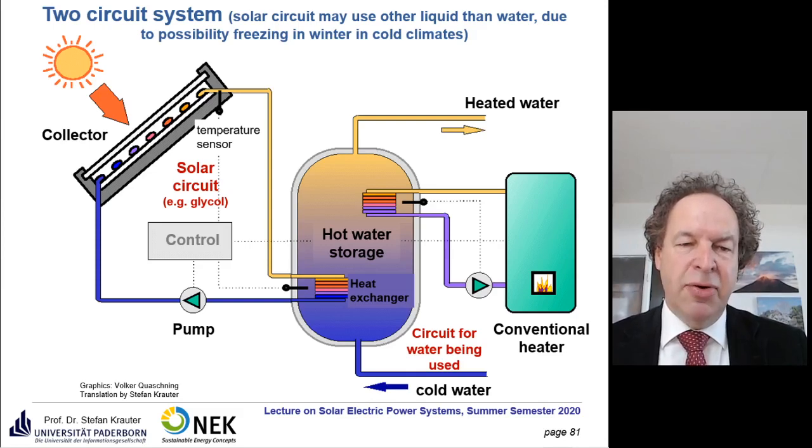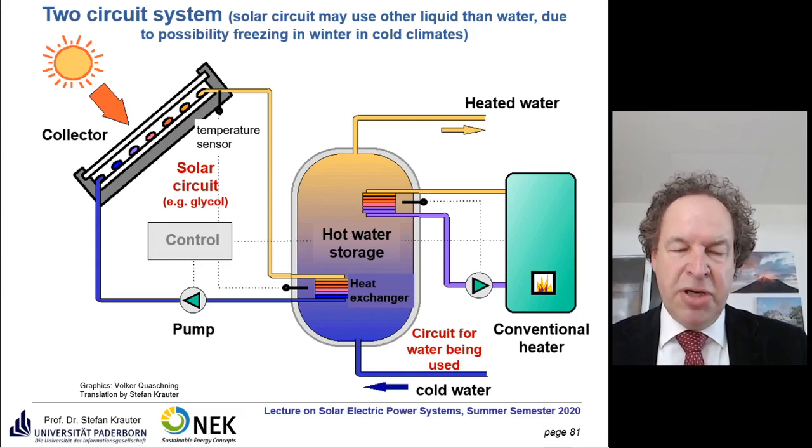Usually it's designed to go down to minus 25 degrees and so on. It works, but you cannot use glycol for taking a shower. So you have to do a heat exchange of the heated glycol with the conventional water here. And while the heat exchanger requires some pressure, it's not possible anymore with the thermosiphon principle.